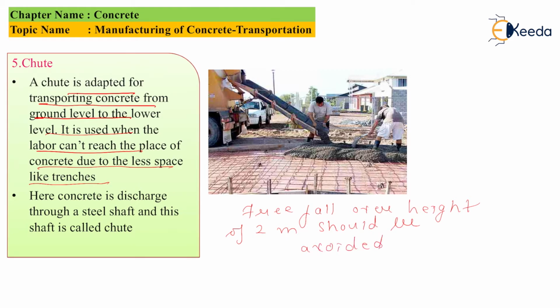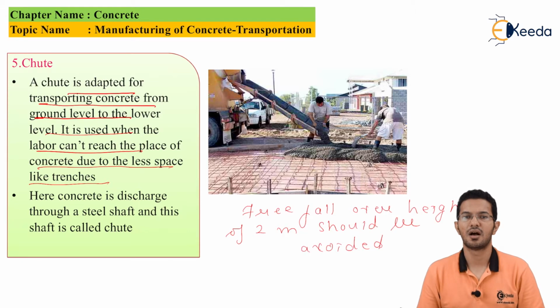Short chutes with proper lower end treatment are used in this process. The concrete should be remixed at the lower end by passing it down through a funnel-shaped pipe or drop chute so that the concrete mix is workable and cohesive. This is simple to use and very much economical. The chutes, which are metallic, half-rounded in section, stiffened at places, may last to handle about 1,500 meter cube of concrete. Long chutes are not desirable as they have the tendency to cause segregation in the concrete mix.